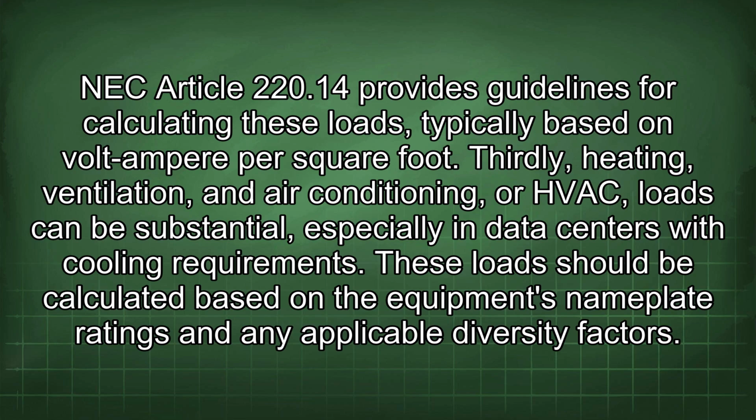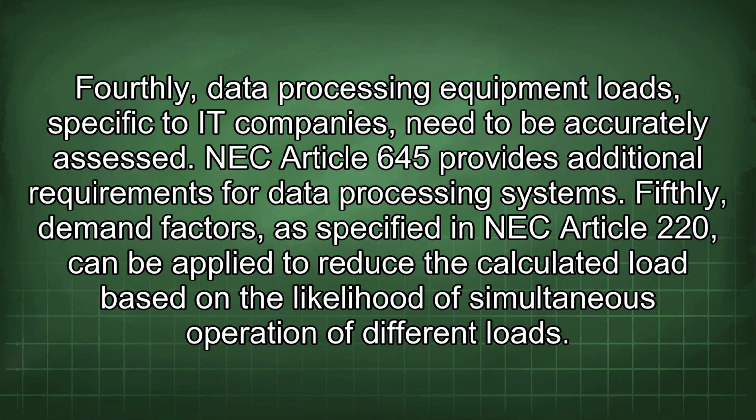Thirdly, heating, ventilation, and air conditioning, or HVAC, loads can be substantial, especially in data centers with cooling requirements. These loads should be calculated based on the equipment's nameplate ratings and any applicable diversity factors. Fourthly, data processing equipment loads, specific to IT companies, need to be accurately assessed. NEC Article 645 provides additional requirements for data processing systems.